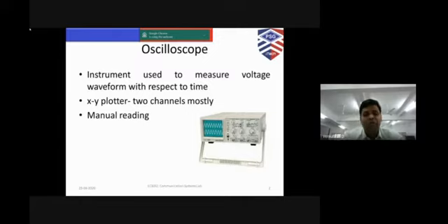And if you have to measure the RMS voltage, then we have to multiply it with 0.707 to get the RMS voltage. Similarly, for a single cycle, you will normally measure the number of divisions along the x-axis and then multiply with time per division, and then it is recorded in your observation or record, and then it will be converted into frequency, right?